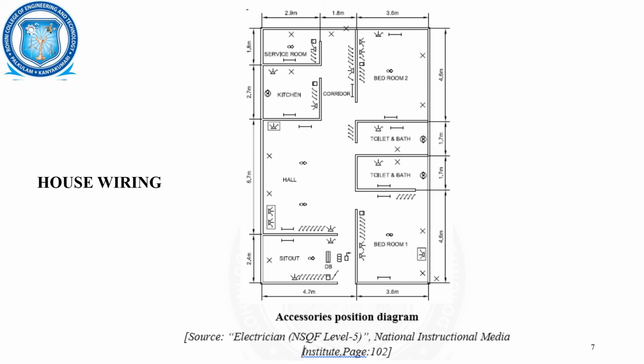It may be a fan, an air cooler or an air conditioner, whatever it may be. The entire room should be comfortable for any human being to accommodate in the room. In such a way, the number of appliances has to be calculated, and then appropriate wiring conditions have to be made. That is, the number of sockets and number of switches has to be adequately designed.